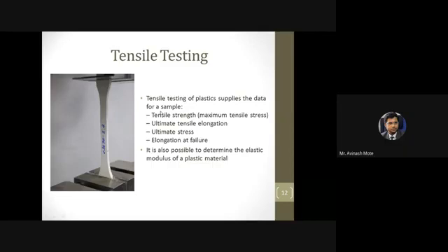Second thing, through the tensile test, you are not getting a stress strain diagram. Clear this picture in your mind. When you appear for quality interviews, such questions will be there for DRDO, ISRO, BARC, or PSUs, or IITs. The stress strain curve is not a direct output of the tensile test. Nowadays digital machines directly give you a printout of the stress strain curve, but that is after calibration.